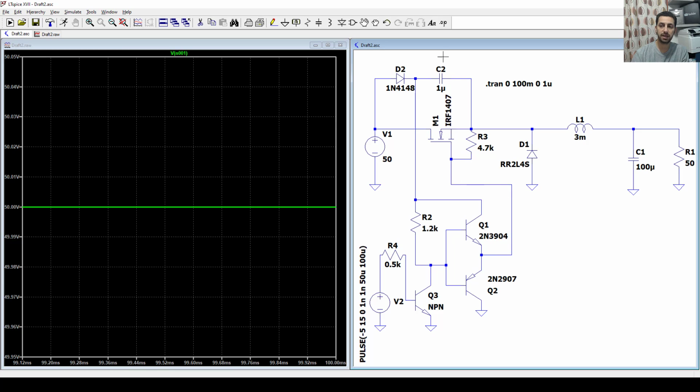Okay, and that capacitor now is already referenced to the source, so the charge of that capacitor, or the voltage, is already above the source voltage. Whatever the source voltage is, it will be above that. So now during the on time, that capacitor will discharge and supply the charge to the gate to turn it on.